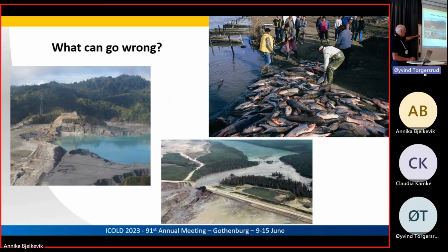This is a 200-metre high dam in pretty steep countryside, and the decant structure allowed the water to go down to tunnels in the foundations that went through the abutments of the dam. It was constructed by putting precast concrete panels progressively on top of some concrete channel structures, and some of those panels failed down at the bottom and led to this outflowing of tailings.